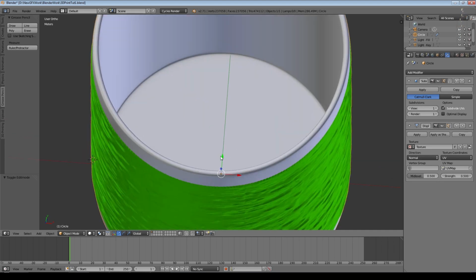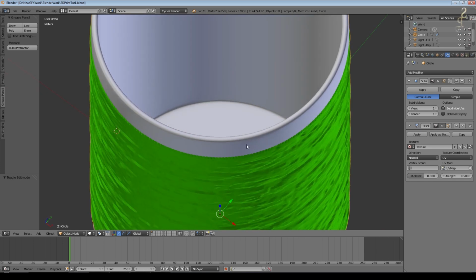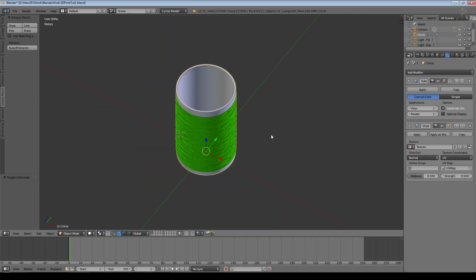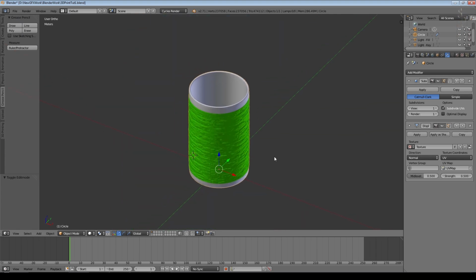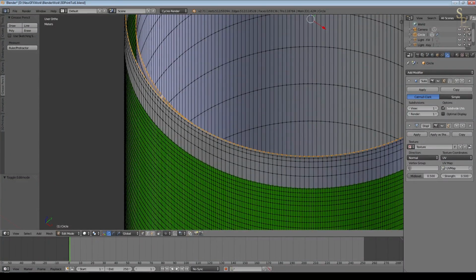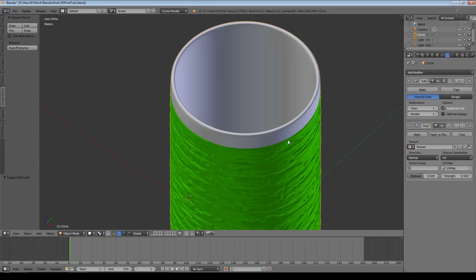And there are some other effects to do with the way that a 3D model is converted into the real world, because obviously a 3D model has finite sections, and that's part of the reason that I like to use a fairly high number of vertices. We can see this model is constructed of little pieces here, and when it prints it, it will tend to smooth out these areas. So what you'll tend to get is it will effectively shrink this internal diameter slightly. That's only really an issue with either very size critical parts or parts that have quite small apertures in them.